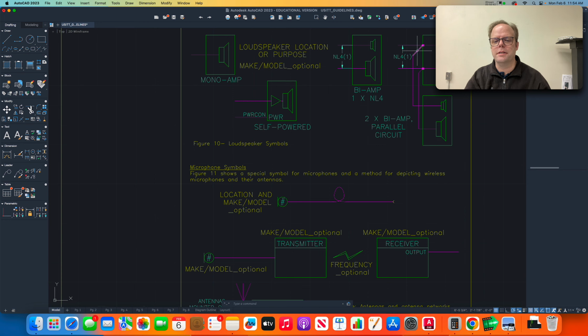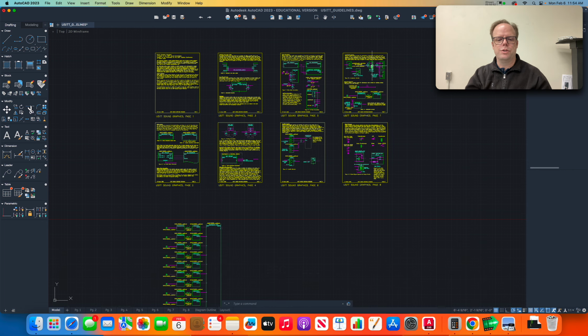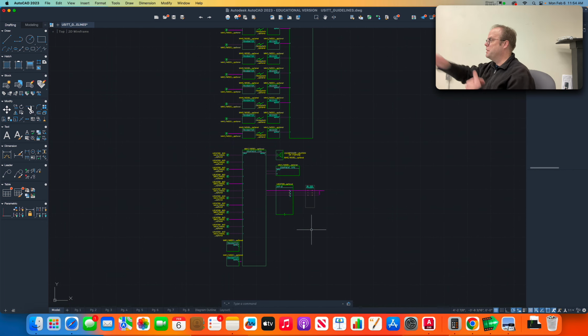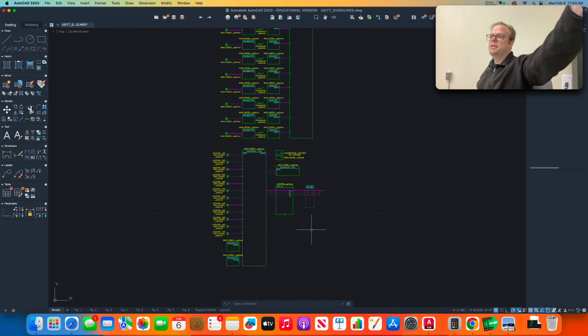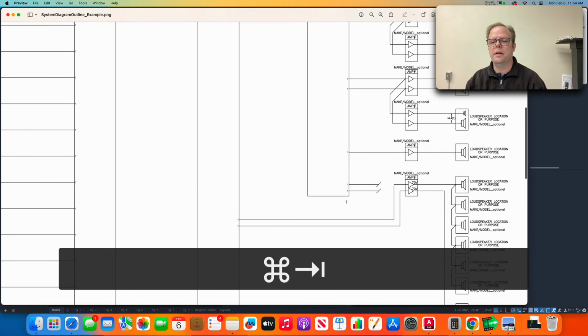There's a little diagonal line right there. All right, so you can copy that and put that down there, right? You can't draw the line, but you can transform it a little bit by trimming or extending it or mirroring it if you need to. So if you need it to be backwards, you can mirror it, flip it around. You can extend it to make it longer. You can trim it to make it shorter.